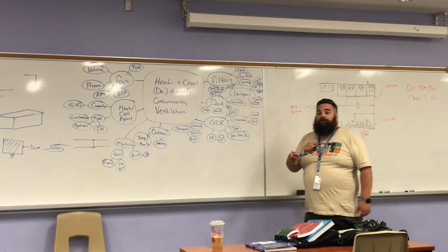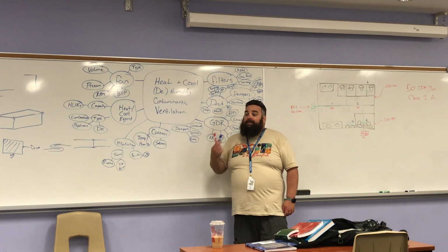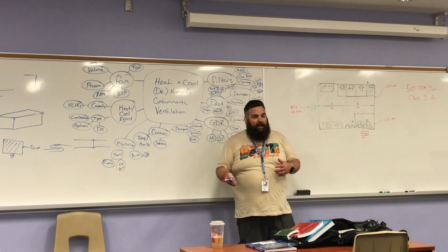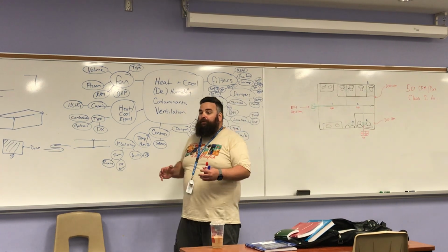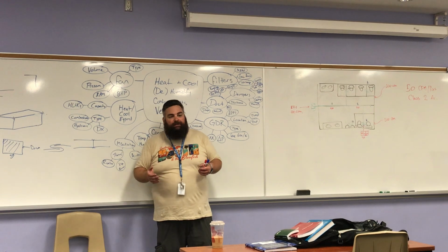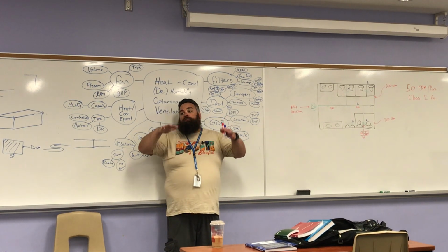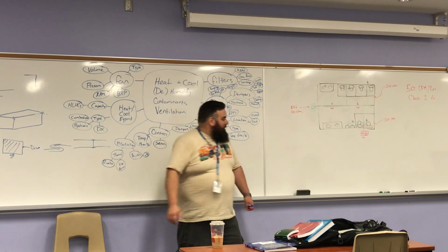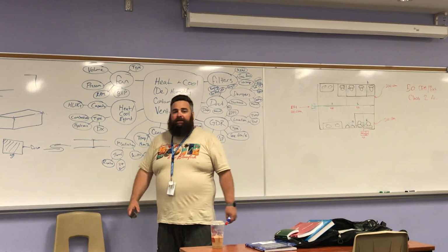And the smaller the duct for the same amount of air, the faster it goes. When we're dealing with contaminants, that's a good thing. There's a trade-off for sound, but if we're trying to keep the contaminants moving through the duct, we want it to go faster. If we slow it down, those contaminants can precipitate out and not be carried to the exterior. Is everybody familiar with what a river delta is?